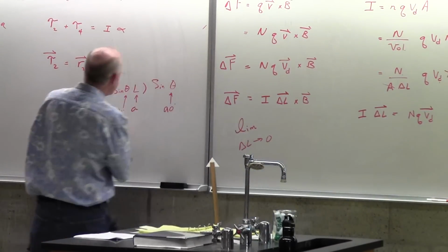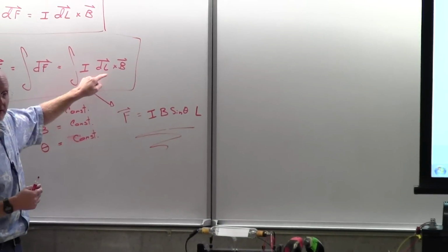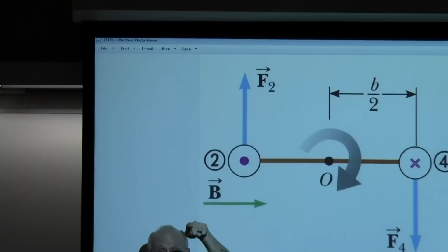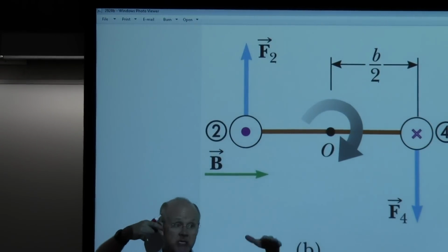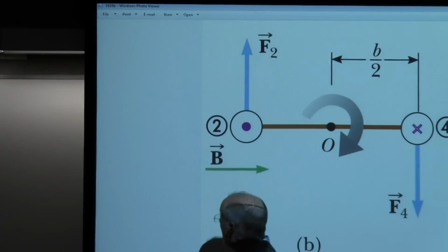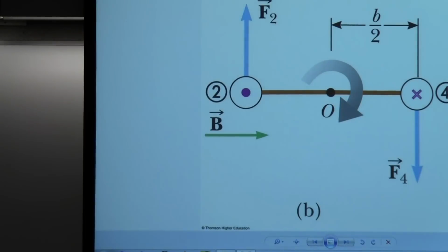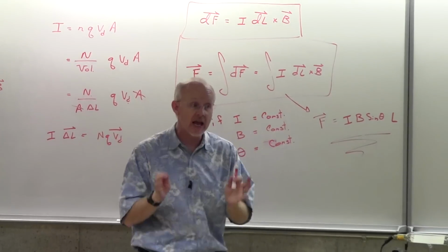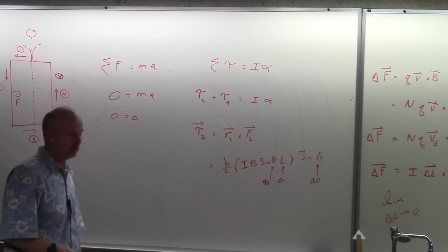So they're both 90 degrees, but I want you to see they are different 90 degrees. Let's look at the first one again. 90 degrees. What 90 degrees is that one from? The wire in the magnetic field. So which way is the wire? Towards you. Which way is the magnetic field? That way. So the 90 degrees I'm talking about is a 90 degrees in a horizontal plane. But then when it came to the torque, I'm talking about this 90 degrees, which is the 90 degrees in a vertical plane. So again, in the simplest case here, they're both 90 degrees, but I don't want you to even think that they are the same angle, and that's why I'm taking some time here to say, okay, in this picture, they are 90 degrees. That's soon going to change.